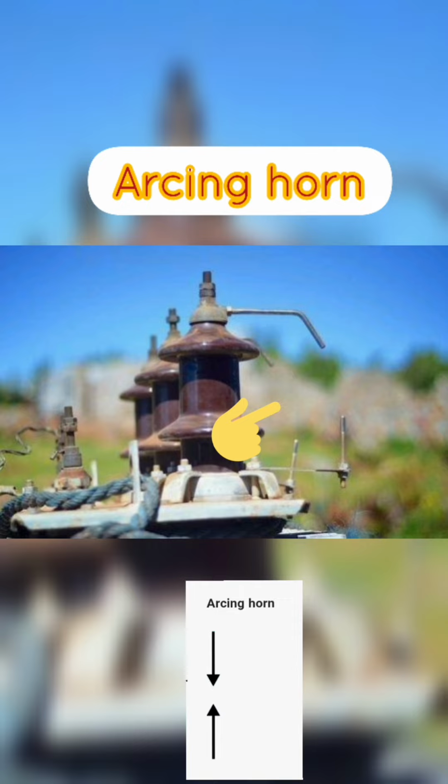This is important because when high-voltage equipment is switched on or off, a surge of electrical energy is produced that can cause arcing between the equipment and nearby objects, such as other pieces of equipment or the ground. This arcing can be dangerous, leading to equipment damage, power outages, and even injury or death to personnel. The arcing horn provides a controlled path for the electrical current to jump from the equipment to the air, where it is safely dissipated.